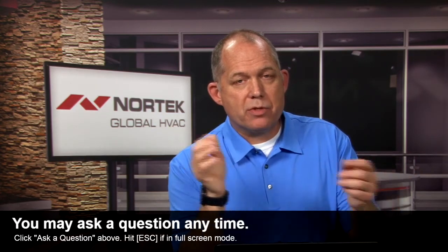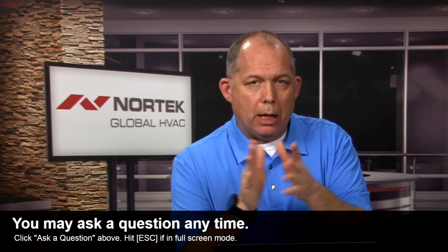Measure your duct static. Make sure you get that blower speed setting based on your duct static. So keep that in mind when you're putting that in there. The airflow is so critical with all manufacturers' units, not just ours, that you need to set that properly. Then you can properly charge the system that way.